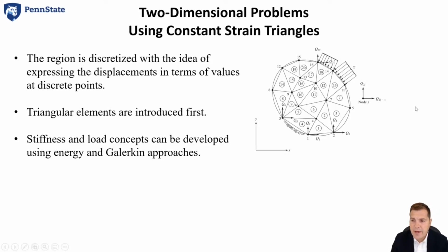The way you do that is by using these incrementation labels. Okay, so you have Q2j minus 1 and Q2j. So let's consider node 1. 2 times 1 is 2, minus 1 is 1, and then 2 times 1 is 2. So you basically have this value for node 1, j is equal to 1, is equal to 1 and 2.